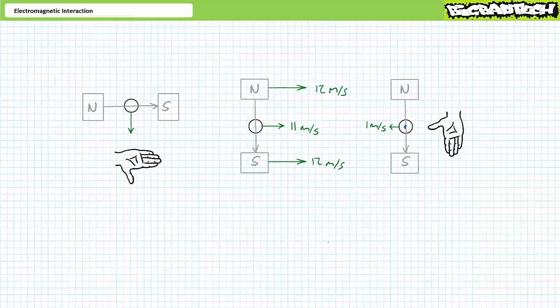As I mentioned previously, this type of relative movement between a moving magnetic field and a moving conductor is also employed in squirrel cage induction motors, where a rotating magnetic field in the stator would move faster than the conductive bars in the rotor, such that current flows on the rotor without the need of physical contact or electrical connection. We'll examine squirrel cage induction motors and asynchronous generators in later lectures.